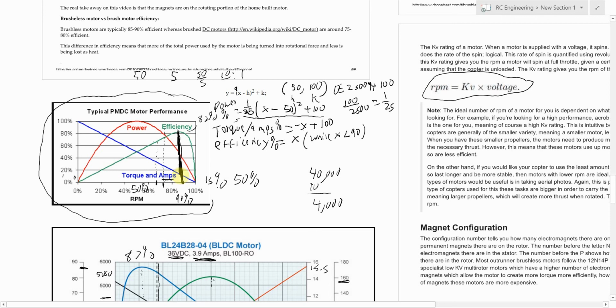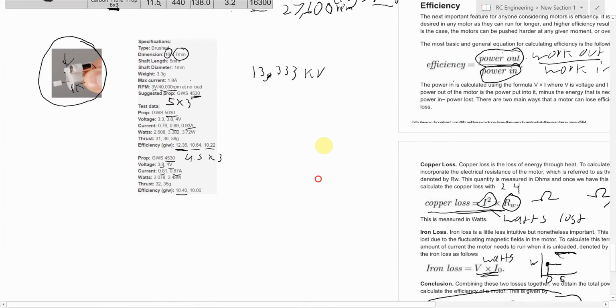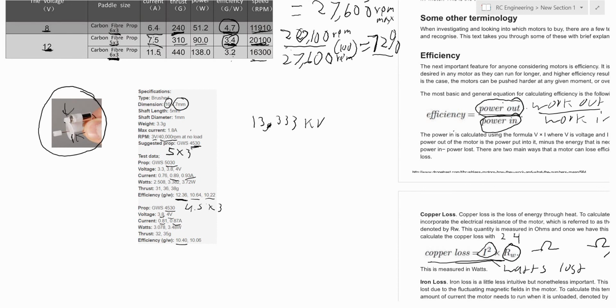What that also means is that your torque will increase by 10. So basically, it's like moving this guy back 10 times, back over towards this area somewhere. So now you're getting the efficiency of something that has very little to no torque, but yet the torque of something that is getting like 25% efficiency. So they're getting the best of both worlds. Because of that, they could use a small motor to turn a very large prop, and they get the maximum efficiency that the motor has possible.